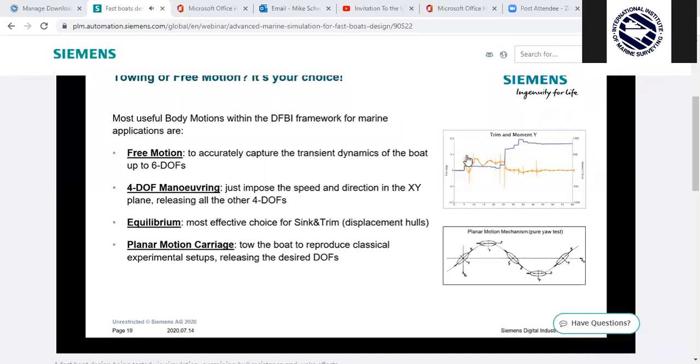We also have a forward-off maneuvering model, where we can impose speed and position trajectory in a similar way you would do in a wave basin test, and we can do that at model scale or full scale. We have an equilibrium motion model, where we can simply solve for the final steady-state position of a vessel statically, negating any transient or porpoising effects, but this calculation is much faster than trying to solve for any of the transient effects in between start and steady-state position.